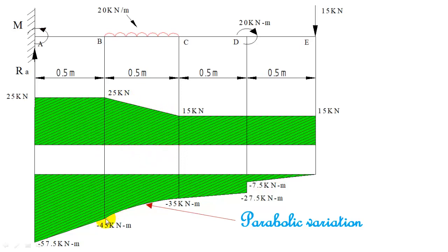And so the curve should move up, and if you draw a horizontal from this point, all parts of the curve should be below this horizontal line, and the concave side should be down. Okay, so you draw the bending moment curve parabolically. You can write down the variation as parabolic variation here to clearly indicate that this is a curve.